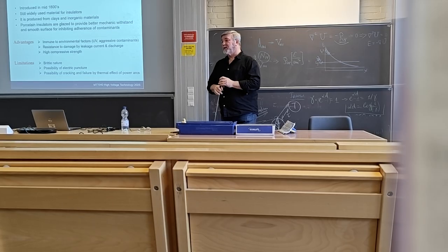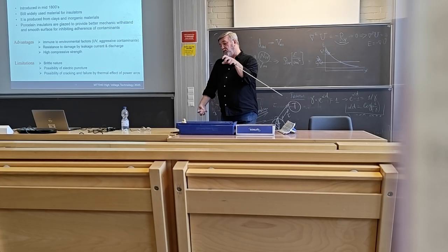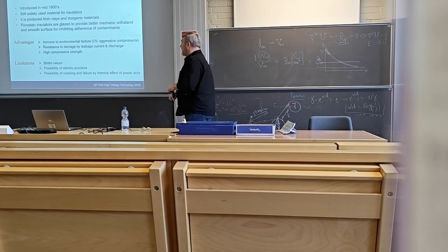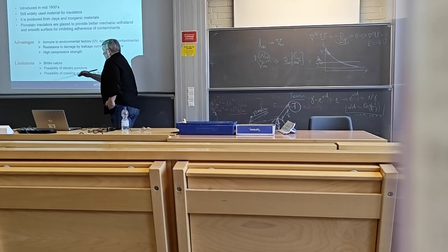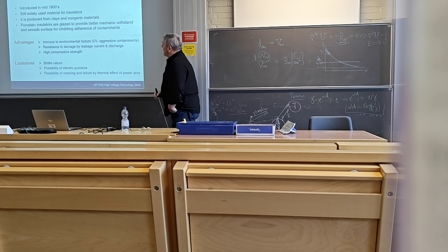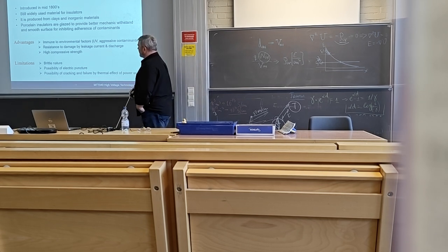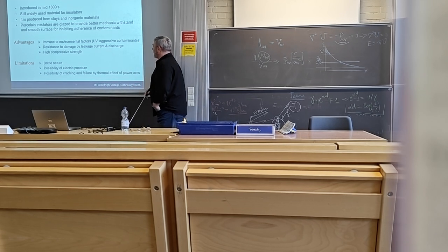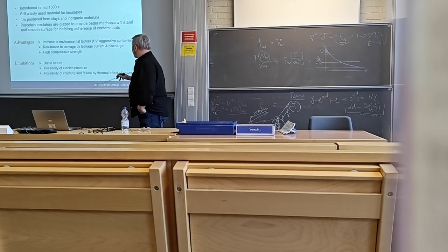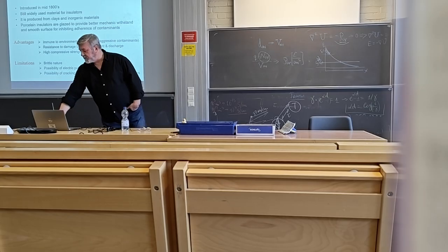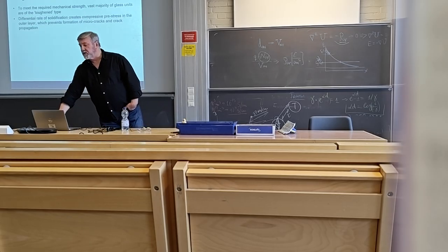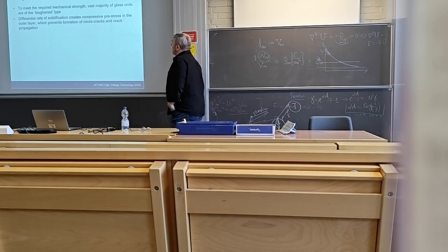But not much will happen actually from the performance point of view, because if it's cap and pin, they are just still there. The shed will explode, but the whole chain will be still alive. But I mean, this is the drawback definitely. Possibility of electric puncture, yes, not often but happen. Possibility of cracking and failure thermal effect, yes. If it's exposed to arcing, it creates thermal gradients and then it will crack.